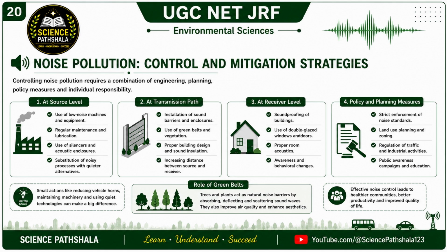Second is control along the transmission path. In this method, barriers are created between the source and the receiver. Examples include sound barriers, acoustic walls, green belts, double glazed windows and sound absorbing materials. Vegetation and green belts can also help reduce noise to some extent in urban areas. The recent example is Delhi-Dehradun Expressway. On the wildlife corridor section of Delhi-Dehradun Expressway, which starts from Ganeshpur and goes up to the Datkali temple, the 12-kilometer wildlife corridor area has the sound barrier installed by the National Highway Authority of India. So that's the best example in transmission path.